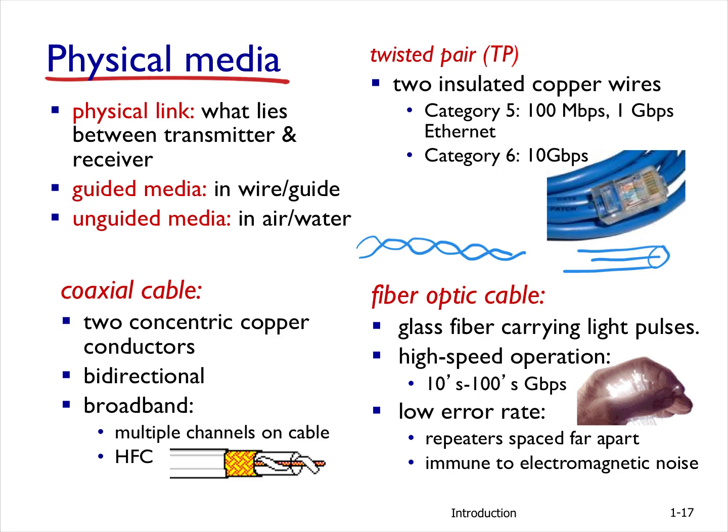The third is quite different. It doesn't have 2 wires, it's only 1 conductor for higher frequencies, and it's called a waveguide. So you have something like this, or sometimes even cylindrical. There is nothing inside. You inject the signal into this, and it travels inside the metal from one point to the other. There is no need for another wire. It's like wireless, but no, it's not wireless, it's guided. This is a wire.